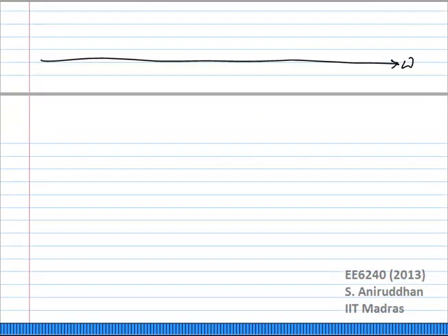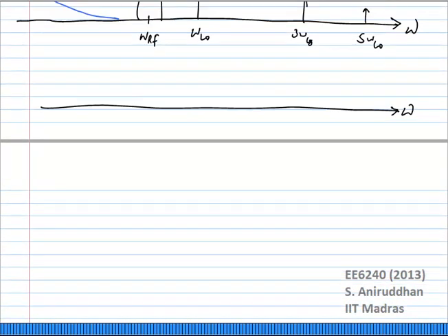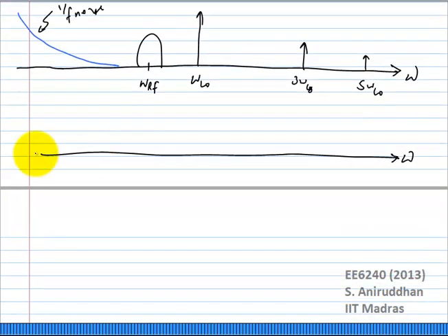So at the output, you get omega IF, but just like your DC, what happened to it? It mixed with the omega LO, 3 omega LO components to form LO feedthrough components at those frequencies. The flicker noise will behave in a similar manner.